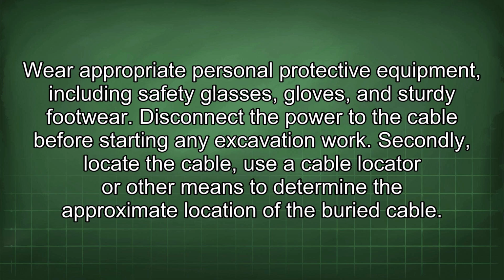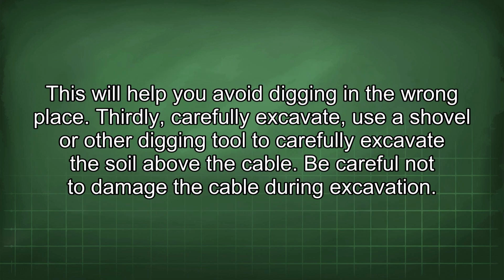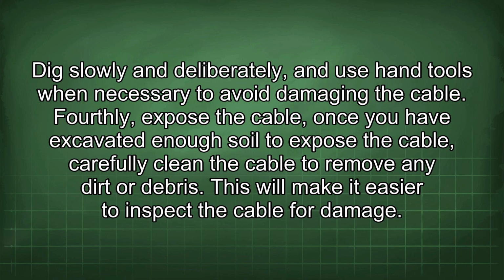Secondly, locate the cable. Use a cable locator or other means to determine the approximate location of the buried cable. This will help you avoid digging in the wrong place. Thirdly, carefully excavate. Use a shovel or other digging tool to carefully excavate the soil above the cable. Be careful not to damage the cable during excavation. Dig slowly and deliberately, and use hand tools when necessary to avoid damaging the cable.